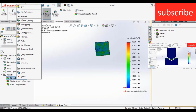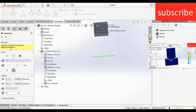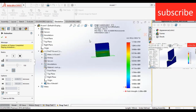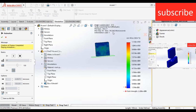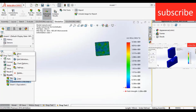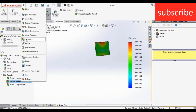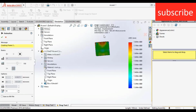Now click on stress, click on animate. Here you see a very interesting thing: all this experiment is done in microseconds, okay, and deformation scale is 1 because I changed the definition. If you saw my previous video, you will realize what deformation scale means.